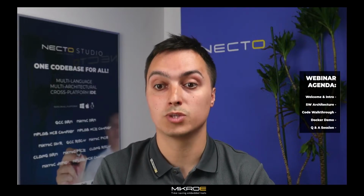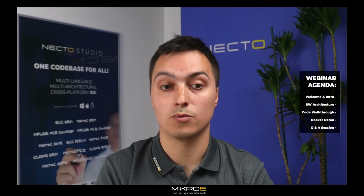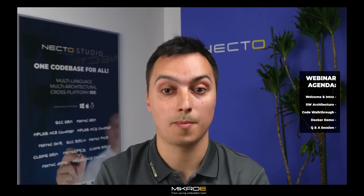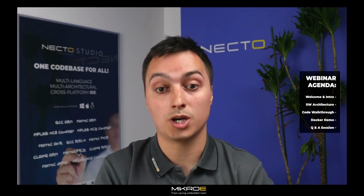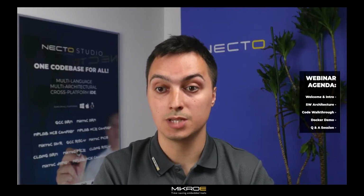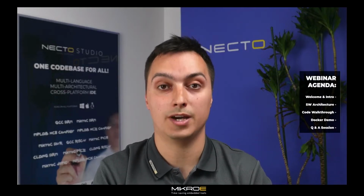You will also learn how to evolve click board examples. So instead of just logging data locally, you will start populating structured buffers ready for remote transmission. I will go further by cleaning up repetitive if-else blocks and introducing cleaner, more fault-tolerant patterns. On top of that, I will show you how to easily switch between transmitter and receiver roles, simply by toggling a line in the CMake build configuration file.